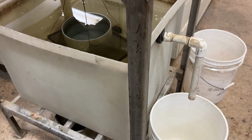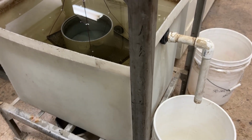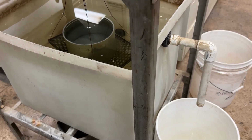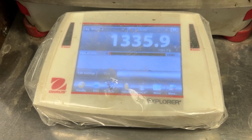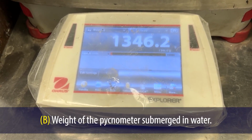While our sample is aging, we will get a calibration of our pycnometer as required by procedure. To calibrate, we need to determine the mass of the pycnometer submerged in water at 25 degrees Celsius. We will allow a few minutes for the water to stabilize. Once we get a stable mass on our balance, we can acquire the weight of the pycnometer in water and record as B.